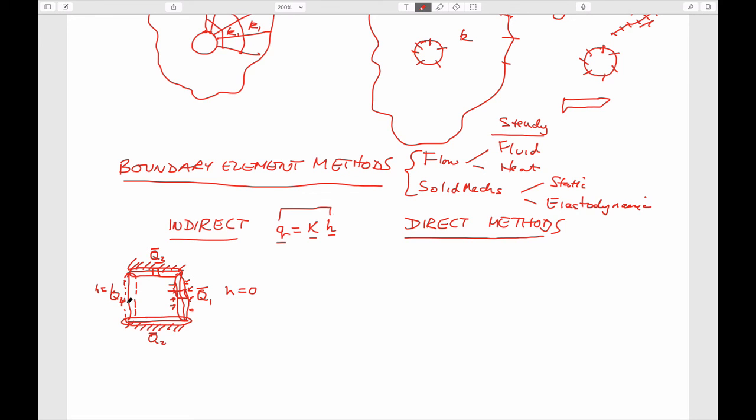So then what we can do is we could apply these sources and figure out what, as a function of these four sources, the strengths of these, would be the complementary condition at each of these points. And so here we know that the flow rate is 0, but we don't know what the head is. So we calculate the head from the complementary condition. Here we know that the head is equal to 1, but we don't know what the flow rate is, so we'd solve this. So this is the one that we'll do a little example with, which is why I say this is, for me, an interesting class, because it takes a topic that's relatively complex, and I think it exposes it to be somewhat more straightforward.